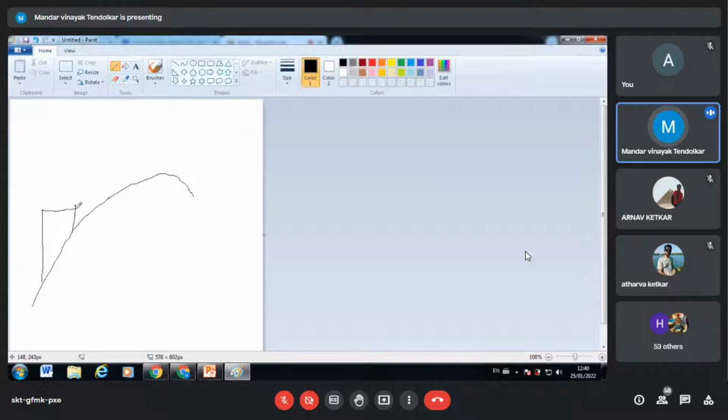Correct? You measure the distance in between them. Then this is 0, this is -20. What we want is -5. So that means 1/4 of this. Let's say over here. Do you agree? Yes, sir. Now take this wherever it cuts the saturation line. This horizontal line is corresponding to -5. This is how you can complete the cycle. Here you have already got the 40 degrees. Here -5. Are you clear?